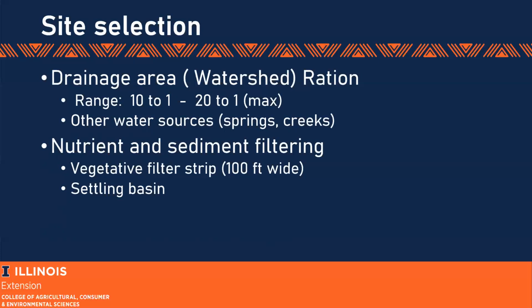So that gives you cleaner water going into the pond. General rule is we're looking at about 100 foot of length to get a good filtration through it. There's some design things in there, but that gives you a good idea, a rough number to work from.